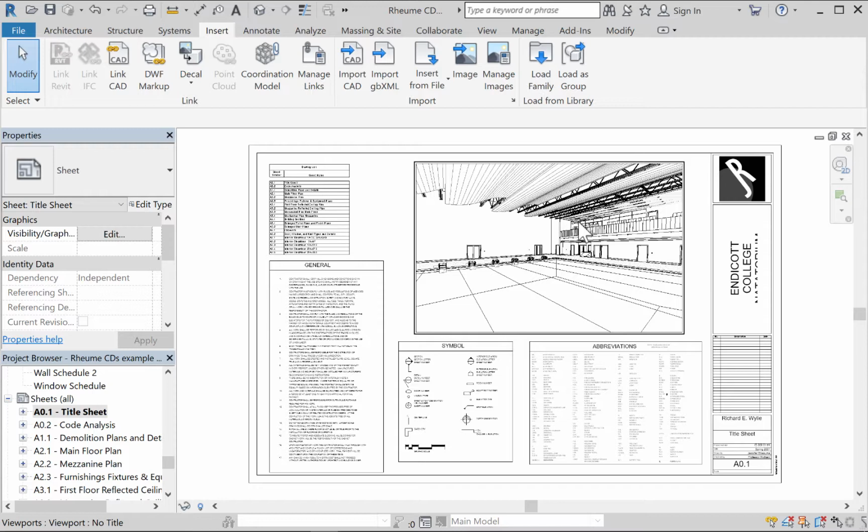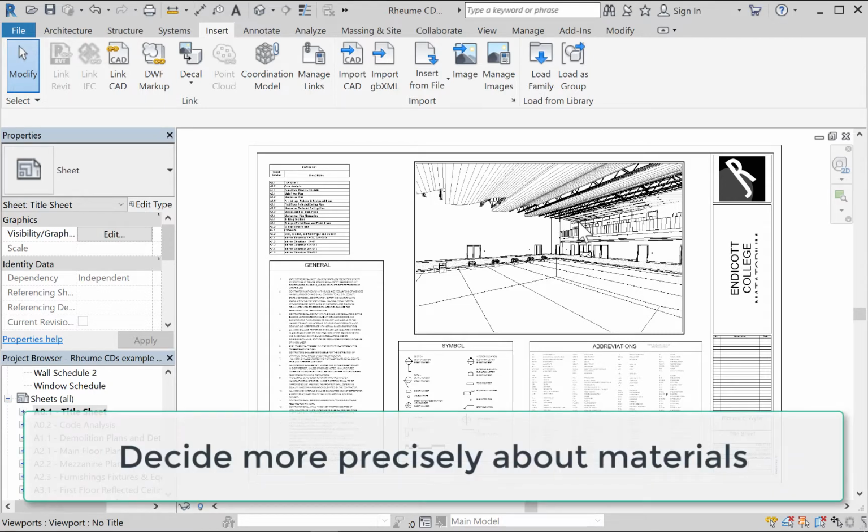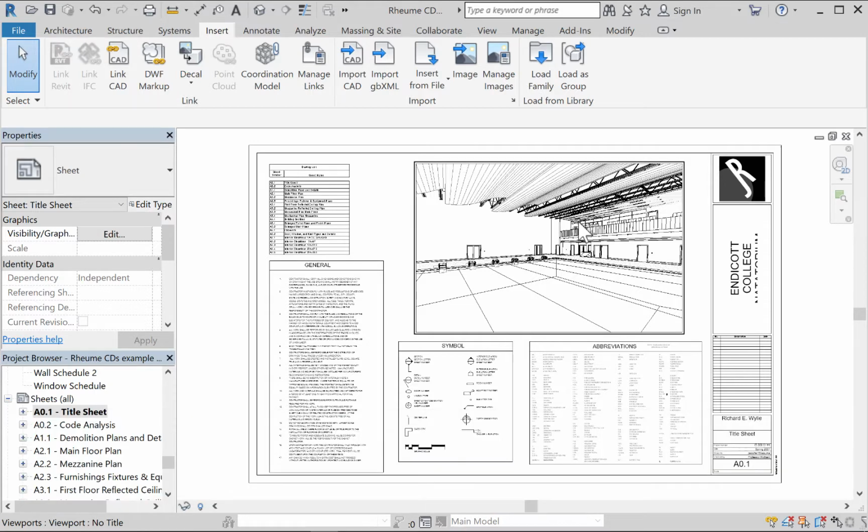You're going to need to decide on finish materials with greater specificity so that we know the dimension of things. For example, tile. Oh, we love tile. It's all the same size, right? Actually, it isn't all the same size. It depends on the substrate that it's going onto, the type of mounting material that you need to glue it to the wall. And then some tiles can be upwards of 3/8 of an inch thick. Some are very thin. Just the cheapest ceramic tiles are quite thin. So you'll need to think about that.